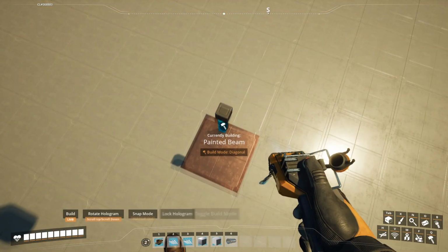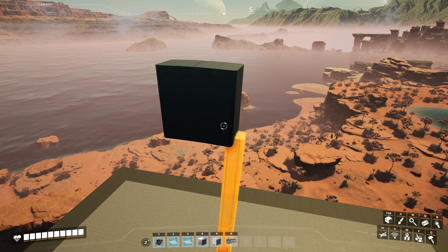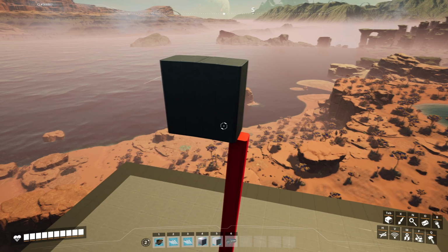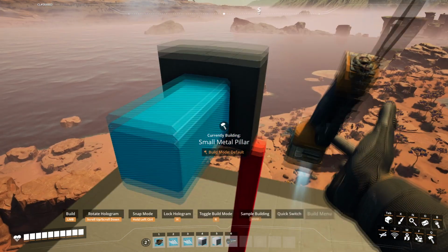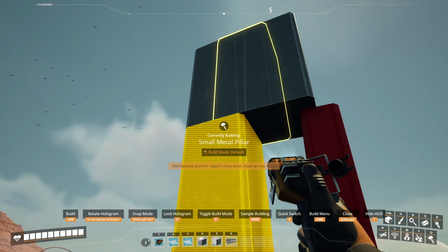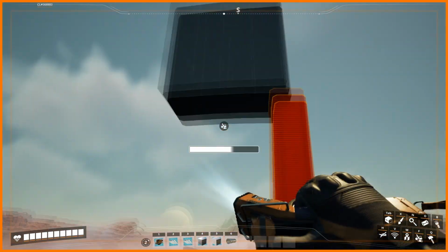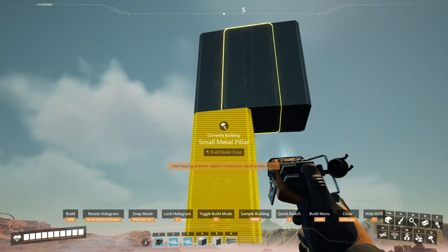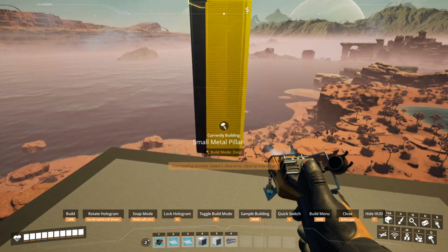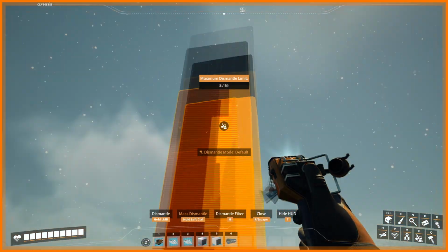And you can do this until you get a full circle. Now I use this method to create most of my bigger circles, and I've used it in other videos. If you want a smaller circle than the 40 meters, you literally just bring all of these lower or further in. So snap to that and then zoom it further in to wherever you want. And that way your circle still stays the same on the outside of the circle itself.